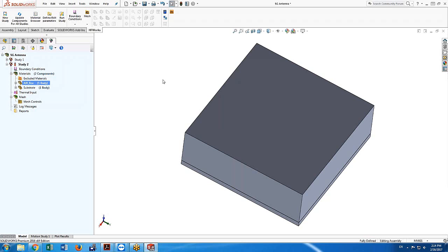So it's important to model the air. This particular case is a patch antenna fed with a microstrip. Then my port is very simple. My port is just this. So that's a port, and I'm going to go ahead and hide.